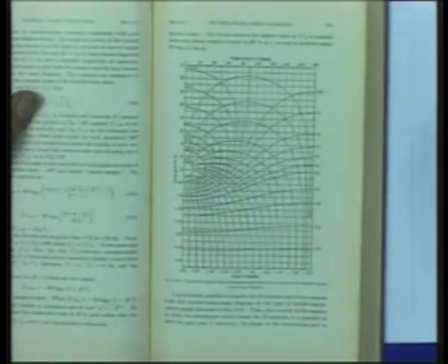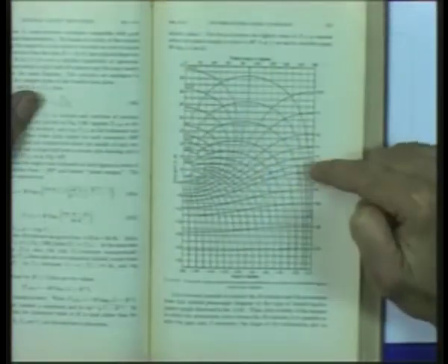I told you that the constant contours, that is contours that correspond to various constant values in the dB gain versus phase shift plane, are not simple circles. They are curves which look somewhat like ellipses, some of them, others are open curves and so on. So, this is the so called Nichols chart that I wanted you to see.